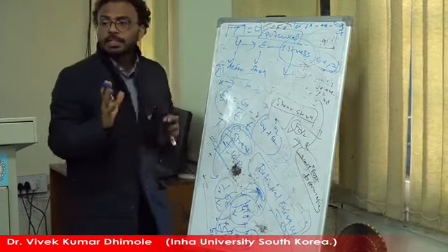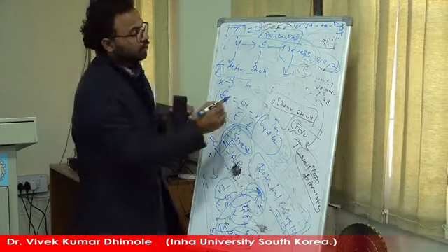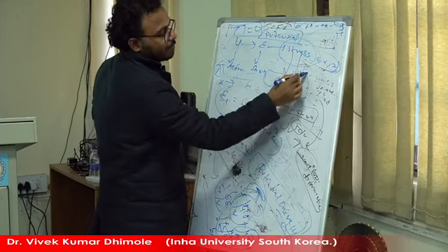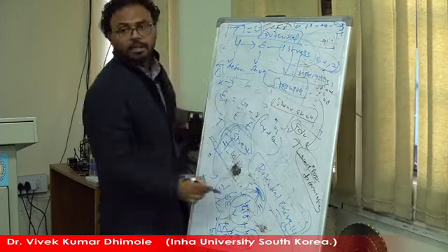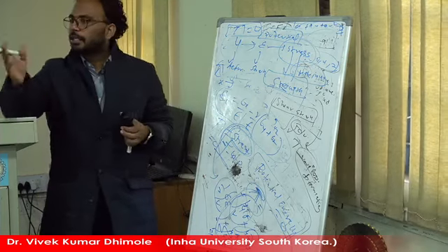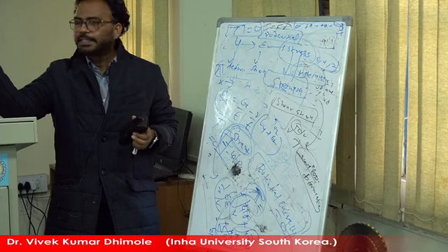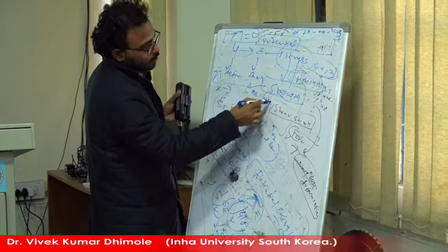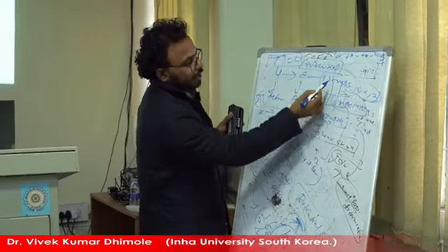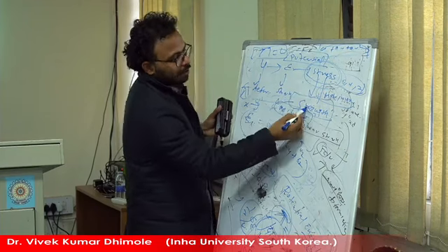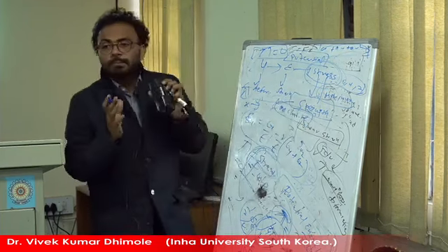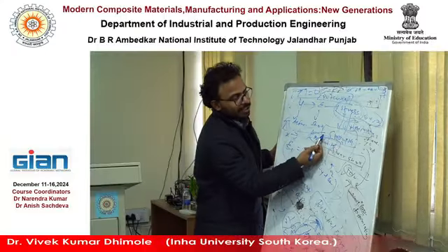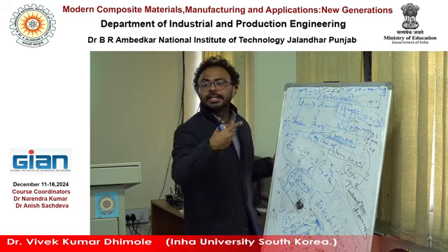Because when you have some structure, it has a strength, and strength is nothing but maximum stress. When you have some structure in bridges or in some machines, it has a strength. This is a mechanical property. You know the strength from the data sheet, and the stress up to the maximum is the strength. So for a proper design, we have to make sure the calculated stress is less than the strength, so that it is under the working limit.